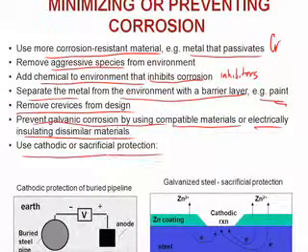Finally, the last thing is to use sacrificial or cathodic protection. This is where we use galvanic corrosion to our benefit. We coat with zinc. The zinc corrodes preferentially and protects the steel. So this is great until the zinc corrodes away, and then you end up with rusty farm roofs once the zinc corrodes away, right? The barn roofs are galvanized. Or we can force a current between an anode and a cathode. You force the current to go in the direction opposite of corrosion. You reduce the corrosion rate.